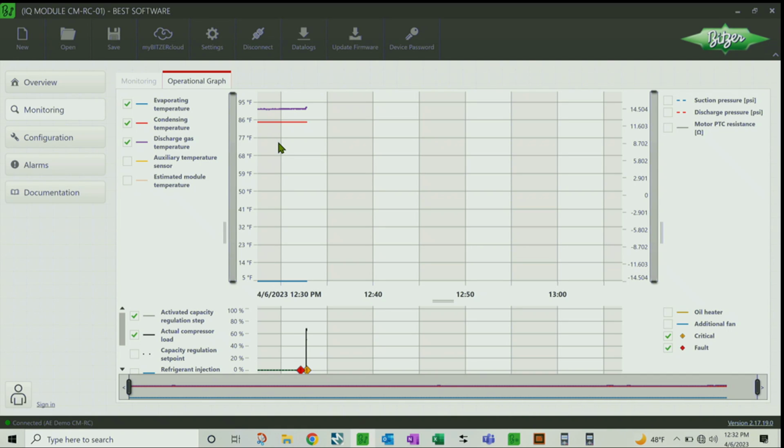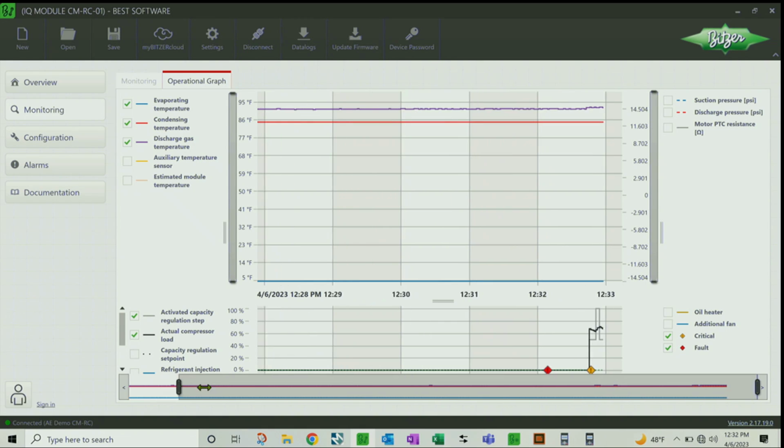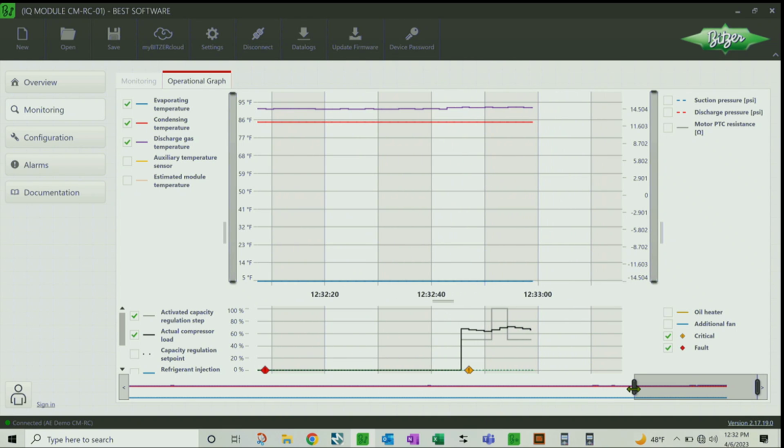So that closes the relays, energizes the coil on the contactor so they can energize. And then down here, you can see that now I am doing supposedly some work, even though it's not really doing anything. But here are your faults. This was your high pressure, I bet. This one is going to be too many timed resets because I didn't wait that 60 seconds.